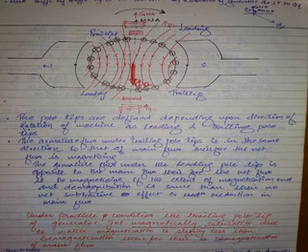So, under the trailing pole tips of the generator, there is magnetization. Under the leading pole tips of the generator, there is demagnetization taking place. Now comes the question. For example, let us consider under the trailing pole tips, the flux density has been increased to some extent. Under the leading pole tip, the flux density will be decreased to the same extent. Yes or no?